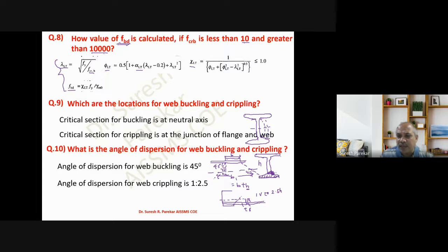We have two root radii, one at the flange and the second at the web. So we take the root radius, and this will be the b value and 2.5 times (t plus r), and therefore you will get b1 or b2, which will be b plus 2.5 (t plus r). Likewise we can find the values of strength, and that will be greater than your shear forces.